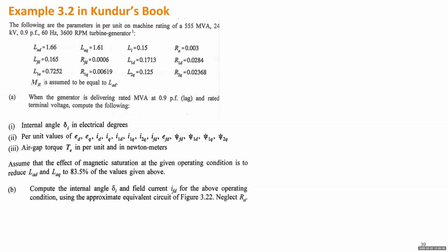Then we merge the two circuits into the same circuit, which is simply just internal voltage, EMF, electromotive force behind the resistance and reactance. If we use that circuit to calculate the angle, compared to the accurate angle, let's see how the difference is. We learn for the round rotor generator, that difference can be very small, because for round rotor generator,